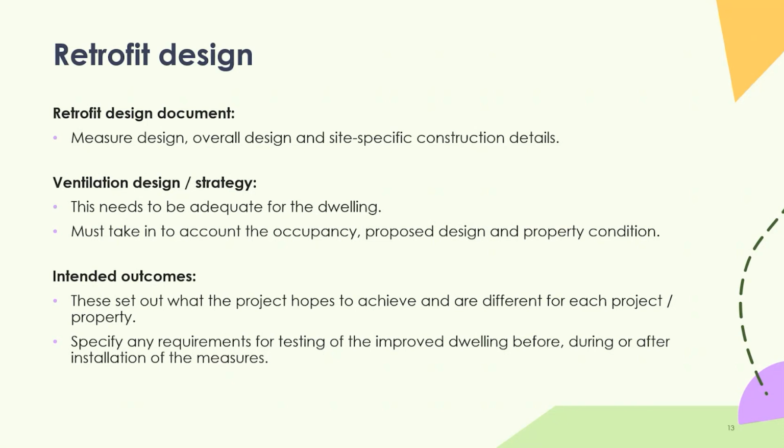And the other thing to make sure about is things like fresh air ventilation in a cold loft space. So if you're installing a full 270 mil of loft insulation from eaves to eaves, you do need to maintain airflow. There are some products which create airflow channels that you can install the insulation right up to, and they're a plastic fitting which maintains airflow across the eaves from side to side of the building. Details like that are really important, otherwise you do risk poor airflow leading to condensation in the loft space, then possibly to rot of timbers in the roofs and things like that. So it might seem like it's a low cost, low risk installation, but proper design is really necessary.